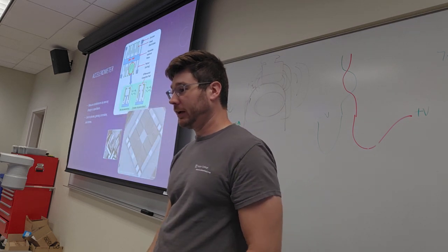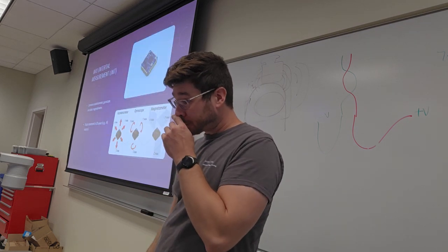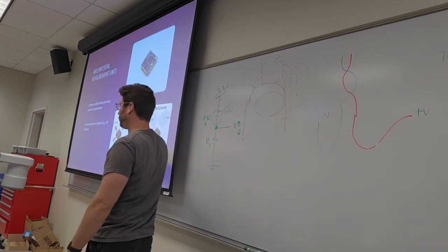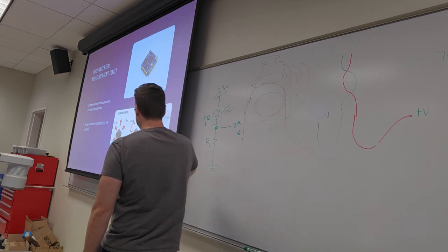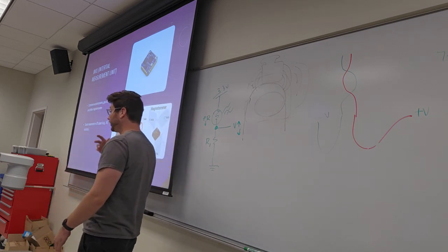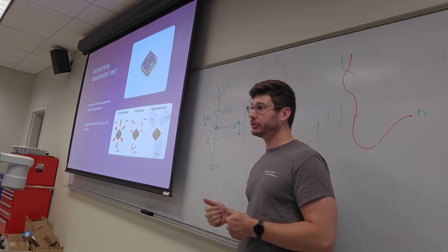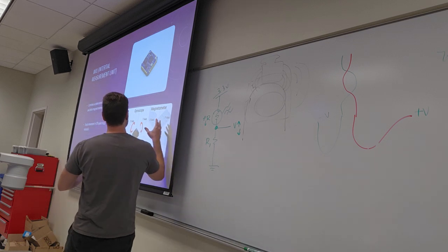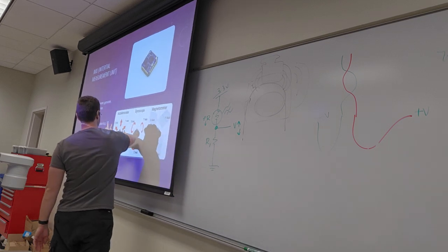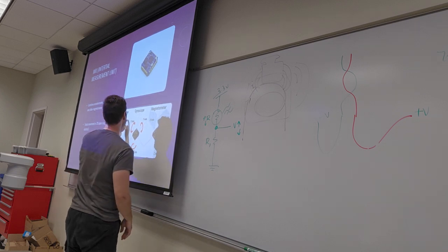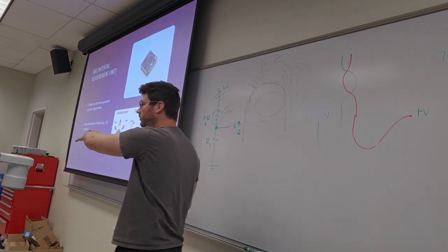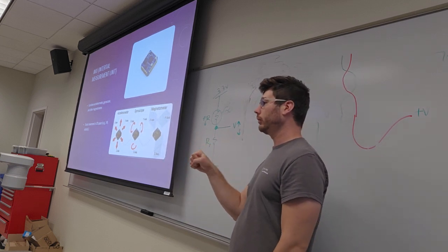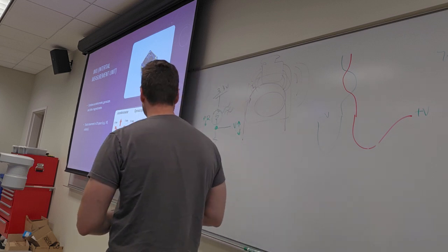If you put an accelerometer, a gyroscope, and a magnetometer together, a magnetometer actually registers the Earth's field, okay? And you do some really high-level math. It's called sensor fusion. It uses artificial intelligence and machine learning these days, right on the chip. But essentially, it uses these three data sources: accelerometer, gyroscope, and magnetometer for each of these axes. Okay, so this is a 9-axis sensor to understand exactly where an object is and how it moves throughout the world.